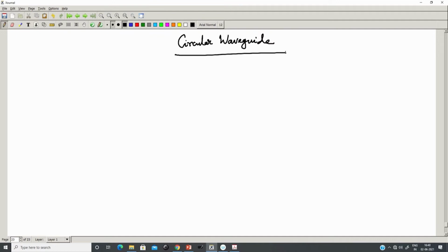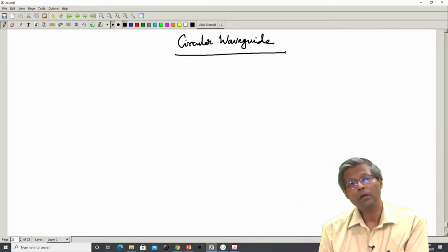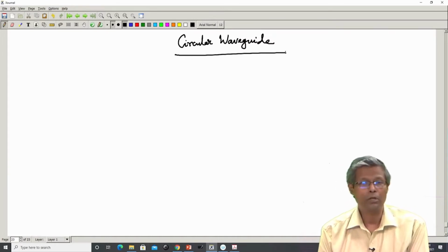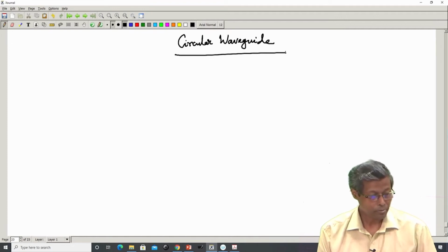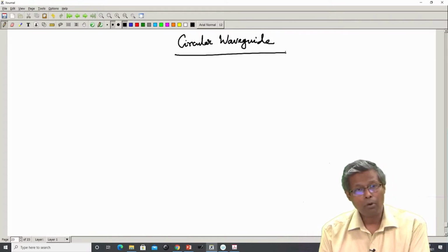The circular waveguide. So, for the modes which are TM to z, we may express the field as we said in terms of the decomposition A equal to uz psi. The solutions we obtained for the electric and magnetic fields correspond to this substitution A equal to uz psi. Now, the field is finite at rho equal to 0. So, the wave functions must be of the form of 16.